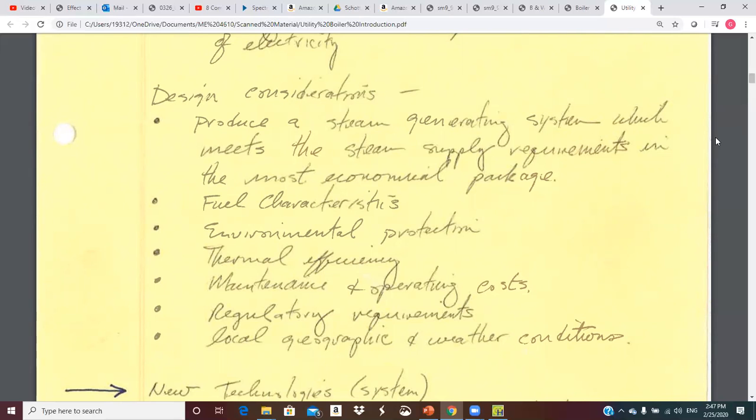Back in the day, coal was probably more of an option. There's probably not many people putting in coal today, but if you're going to burn coal, there are different types of technology. There are what they call stoker spreader type boilers that burn chunk coal. You can have 1 to 2 inch chunks. You just dump them out on a conveyor. It rolls into the firebox and burns.